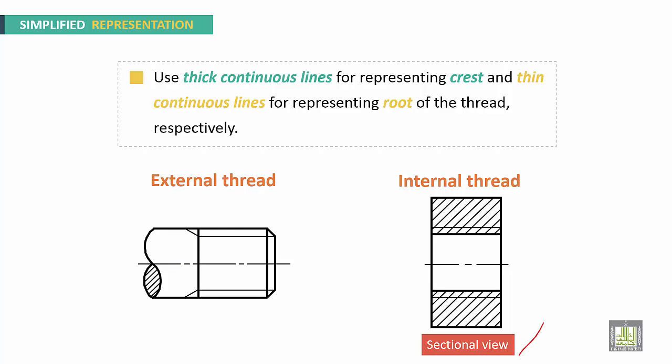Here we have sectional view for internal thread. You can remark here that the hatching lines will cross the root lines. Okay.